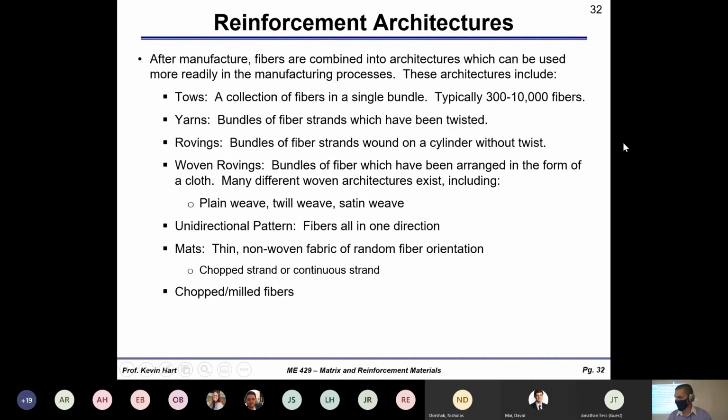So crazy. All right, that tow you noticed is very straight, okay? It's not intertwined or interwoven, all right? All the strands are in line with each other, okay? And so that individual tow has this very flat architecture. That's different from a yarn, where yarns are woven into each other and it's not all straight together, okay? You have a question?